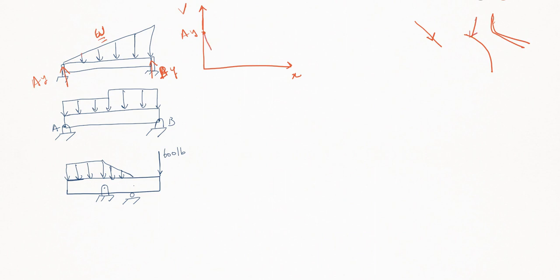So it's gonna keep going. There's nothing happening until we get here. What do we have? We have BY. So it's gonna go up until 0. Now notice this is actually gonna be the value of BY. Now if we wanna draw the moment of this, we have moment X, so it starts at 0.